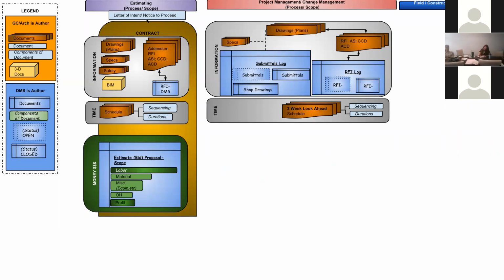In regards to drywall, they chunk it out. I've seen them do it one of 2 ways. The first way is they'll ask us to do one side, meaning we'll install the drywall on one side, which will allow all the other MEPs and everything to get inside the walls. They'll be able to do inspections. Once everything's then approved, they will then refer to it as second side or wall close-up. Once we then do the other wall close-up, then the wall is ready to receive taping.